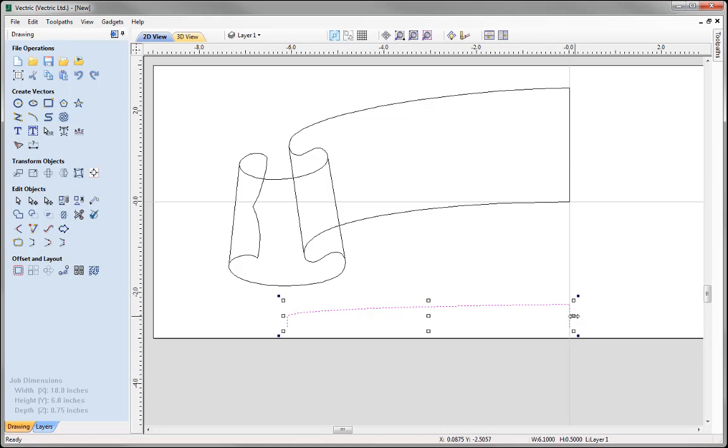And if I press Control on the keyboard and then take the right hand side here and drag that in, it's going to create a copy of the component. It's just going to shrink it to the width that I select. I want to do it roughly at the same width as the fold that we've got here, so that seems to be okay. And now we need to edit the shape of this cross section. Here, the fold is actually going to come underneath the main fold here, and it's going to come up a little bit towards the right hand side.